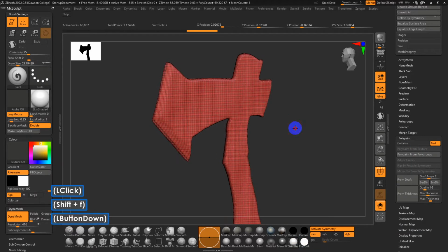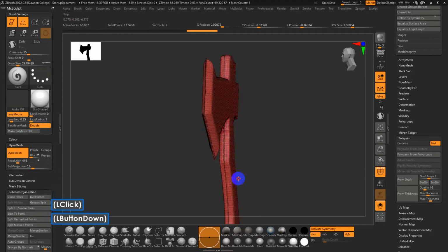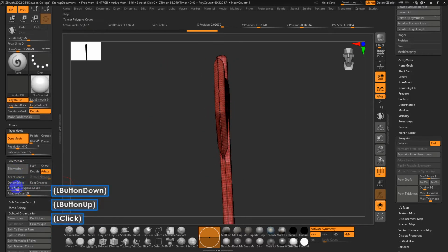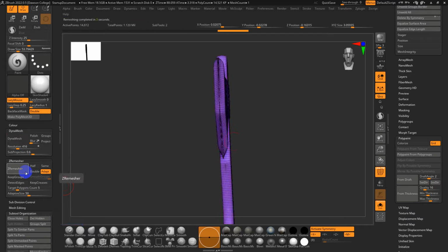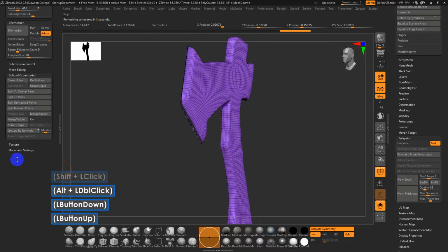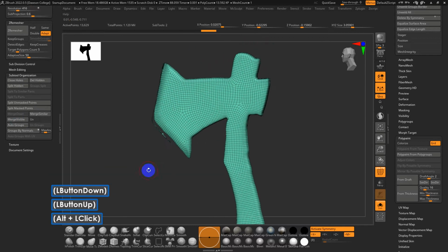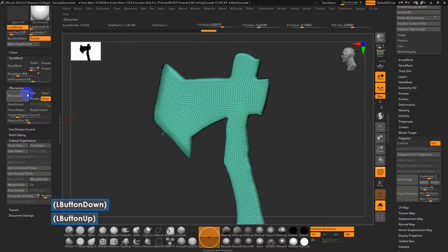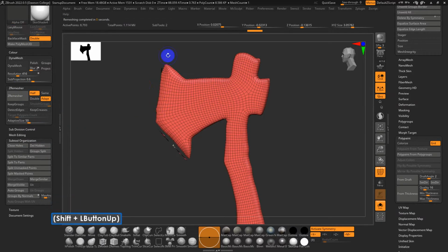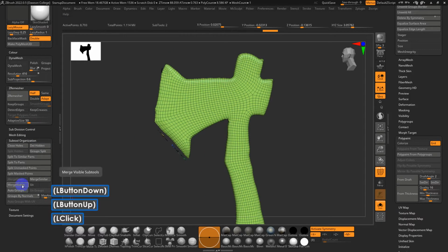And what I'm going to do very quickly is let's have symmetry on. Symmetry? There we go, symmetry. I'm going to Z-remesh this, very low poly count, Z-remesh. Again, it is a little bit messy, just be aware of that, because there's some messy mesh there, but I'm showing you a rough condensed workflow here. Let's see, remesh in half. Groups.